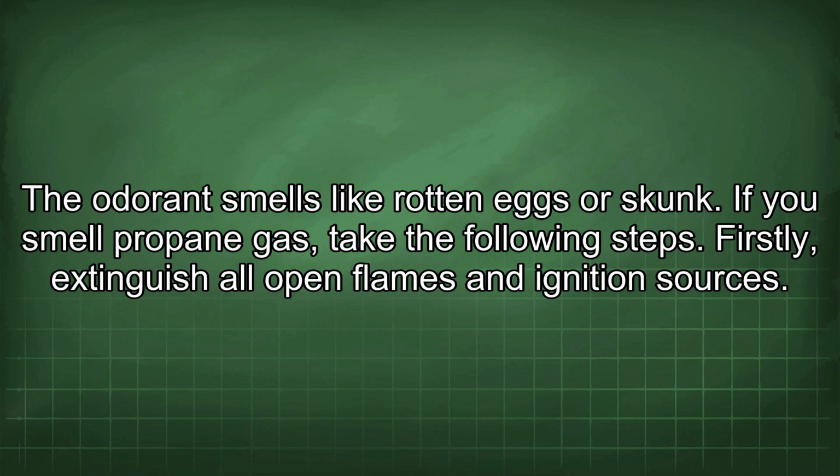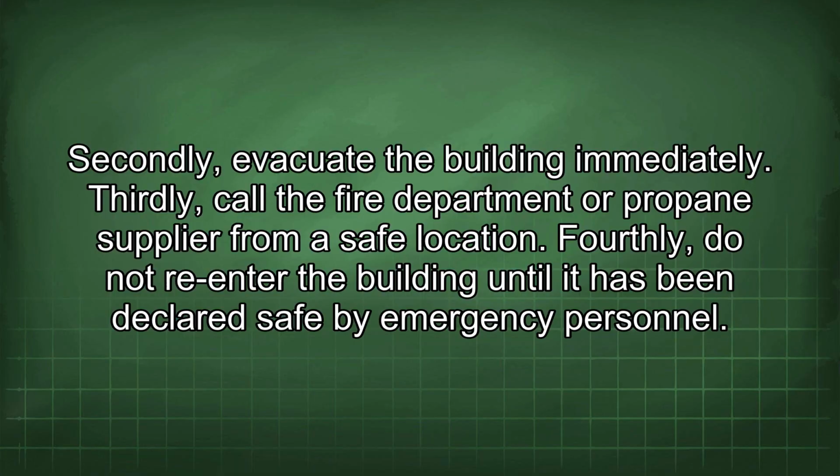Firstly, extinguish all open flames and ignition sources. Secondly, evacuate the building immediately. Thirdly, call the fire department or propane supplier from a safe location. Fourthly, do not re-enter the building until it has been declared safe by emergency personnel.